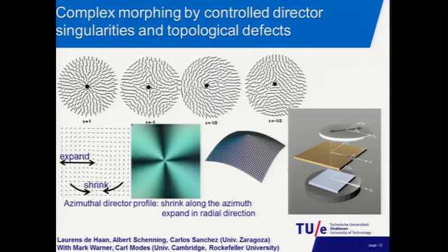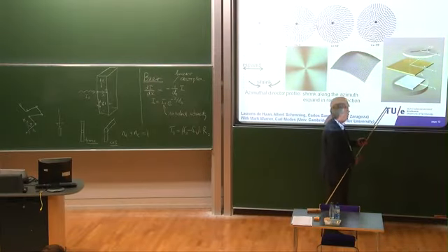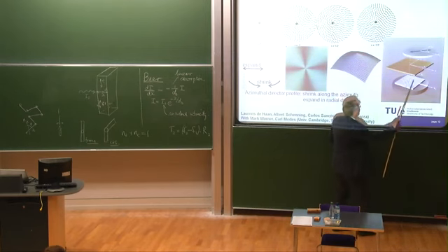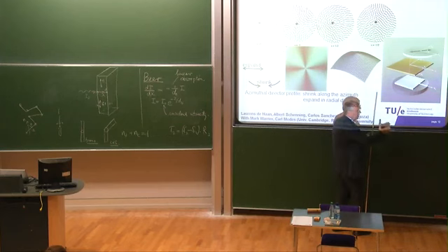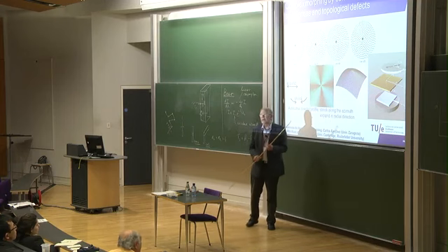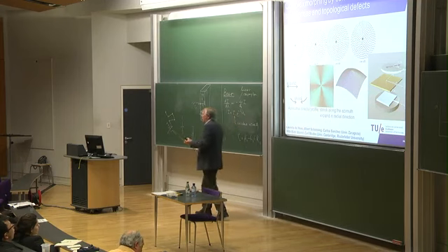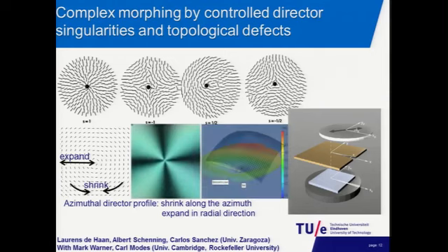This is our substrate coated with a photo alignment layer, in which the orientation can be set by exposing it with polarized light, and we rotate either the mask or the sample, so we gradually modify the whole substrate with an orientation layer. You can bring two of them together, fill it with liquid crystal, polymerize it, and then you have your film made.